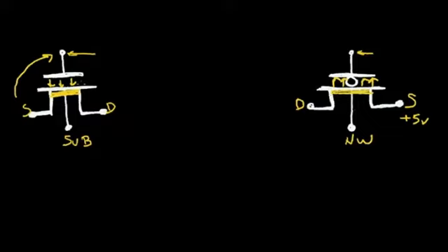And recall that as I increase the drain voltage, the structure of this channel changes, and the electric field of the drain region decreases, so the channel can become more like this. And sometimes I like to just look at the symbol and look at the different voltages, and in my mind think of how this channel works. And that helps a lot when later you use these symbols to do circuit design.